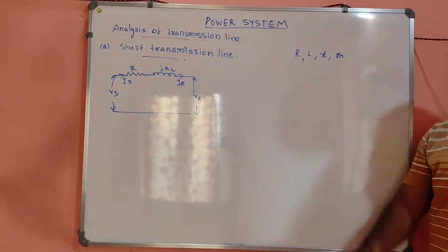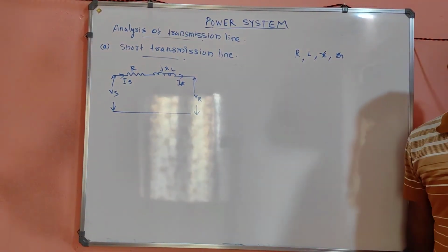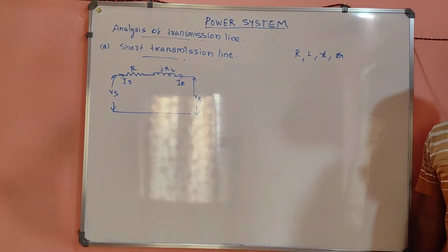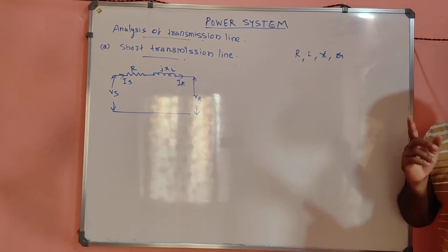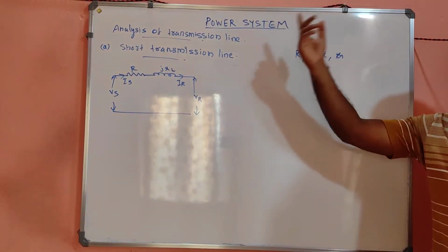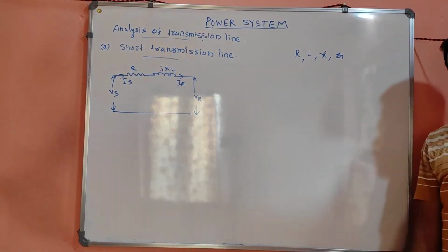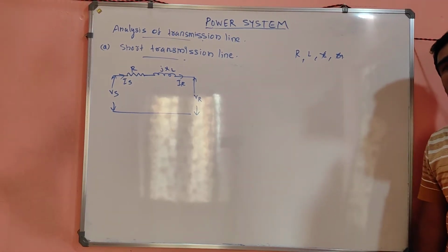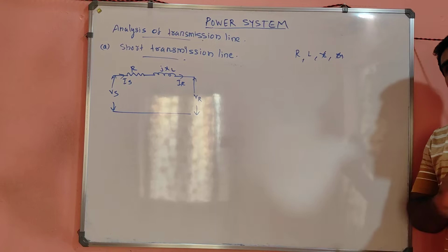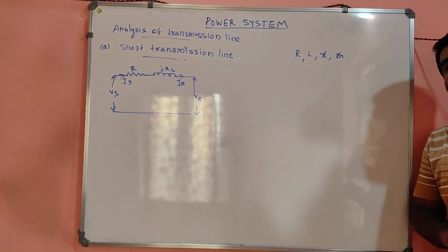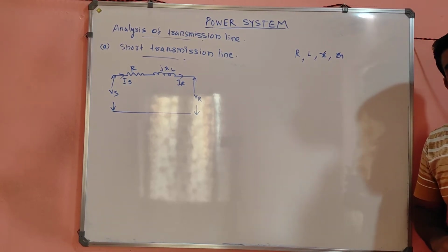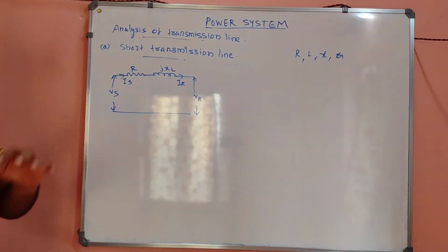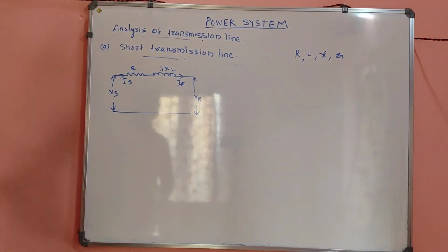Or you send 100 volt there and you just received 120 volt. What is the meaning? My God, there is a short transmission line now, receiving end voltage greater than sending end voltage. What will it be? Oh, there will be the effect of capacitance. So that may be either a long transmission line or a medium transmission line. That conclusion you have to make from the analysis. It's very deep actually. So you just note it down, my dear.